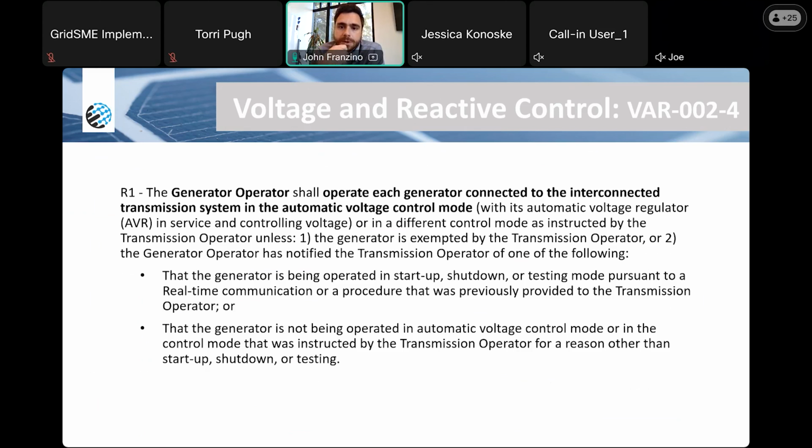So one, the time horizon is tight, 30 minutes, and two, oftentimes, especially in the IBR world, maybe the original SCADA integrator who developed the HMI wasn't really aware of R2 and the criticality of AVR. So it's not really a status or a set point that is visualized in the HMI to operators and highlighted as much as it really should be.